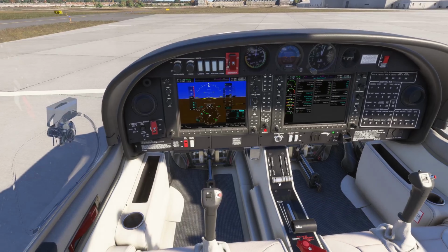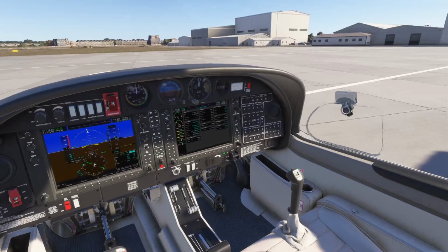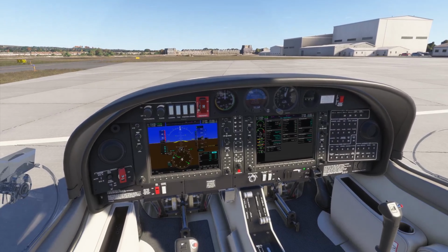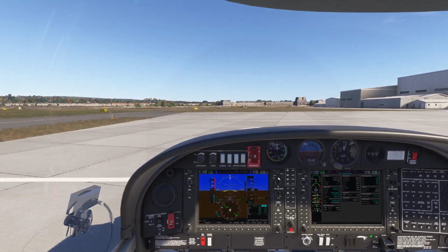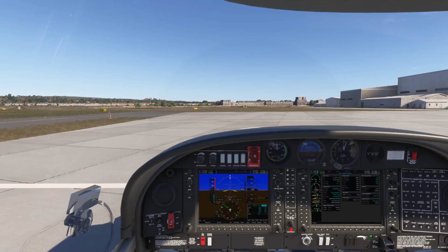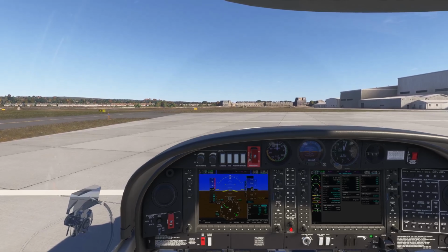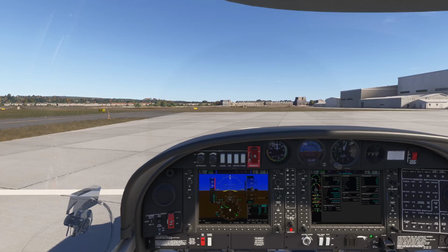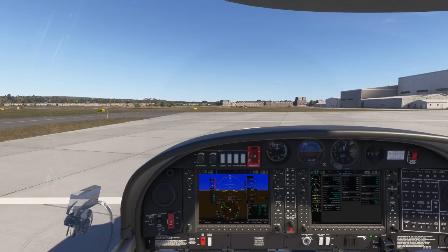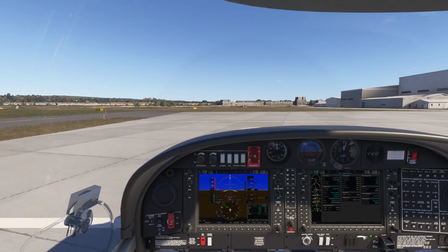We're going to release the brake after looking left and right clear, and we're going to put a bit of power on to get us moving, idle the power, and check the brakes. The brakes work. Good. So we can now continue taxi, and you don't need a lot of power to taxi. Fast walking pace is what you'll be told to do.